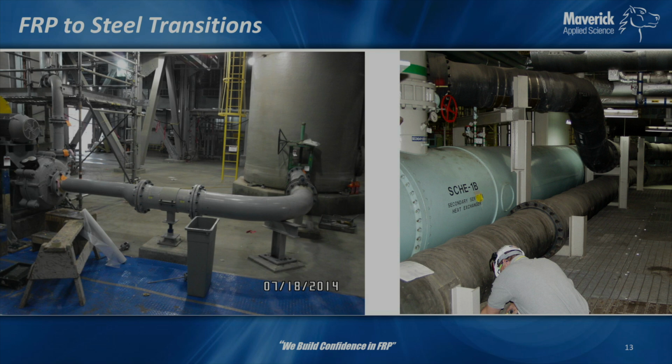This is actually a good example because you see, maybe this is 10-inch pipe, something like that, and then maybe next down to 6 there, but support there, support there, support there, probably another support right underneath that valve. So in 20 feet of pipe, you see 4 supports. Because there is probably 800,000 to 900,000 pounds hanging off of that. So you don't want that much load hanging off your FRP.